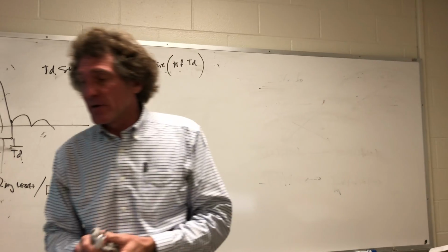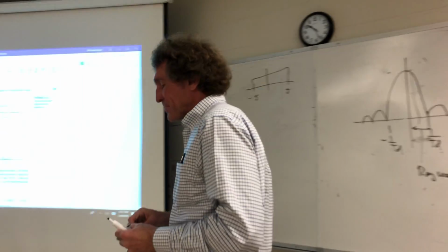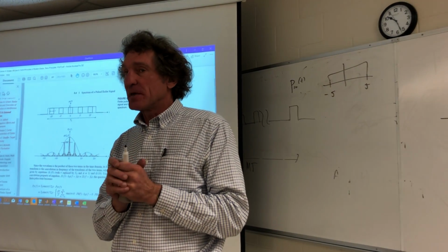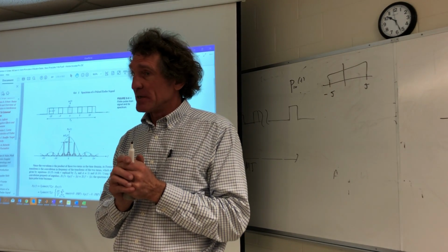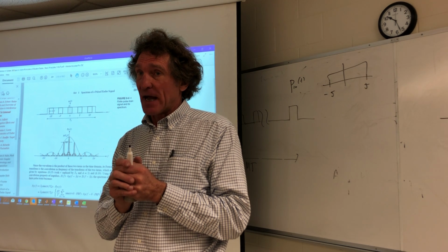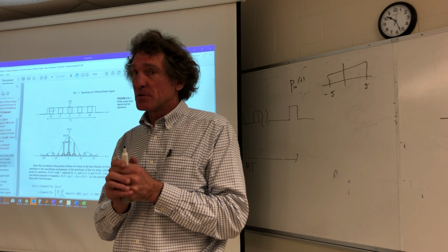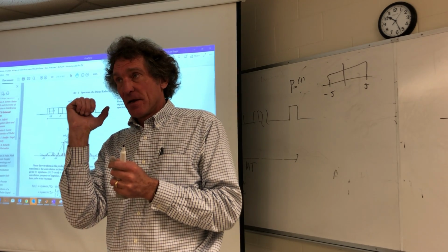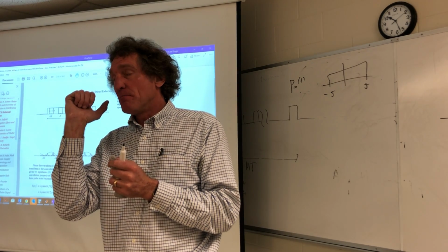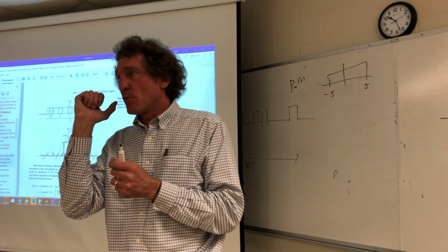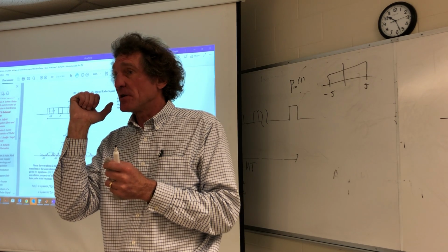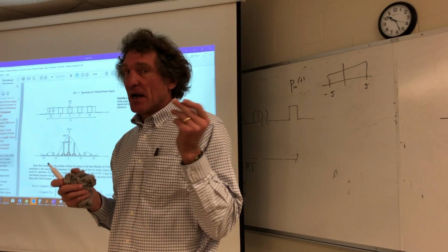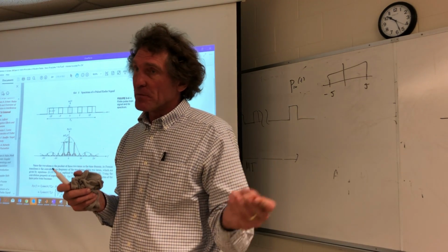Now, with aircraft, this is where it gets bizarre. The faster something's going, to know the exact speed it's going, the more pulses you have to gather in. And that means if you want the exact speed on an F-16 coming at you, you're gonna have to lay there a long time. Most times exact speed isn't the important thing. If you're within 10%, that's all you need to know. You need to know it's coming, and it's coming fast, or leaving and leaving fast. And you need that for a lot of things with armaments.